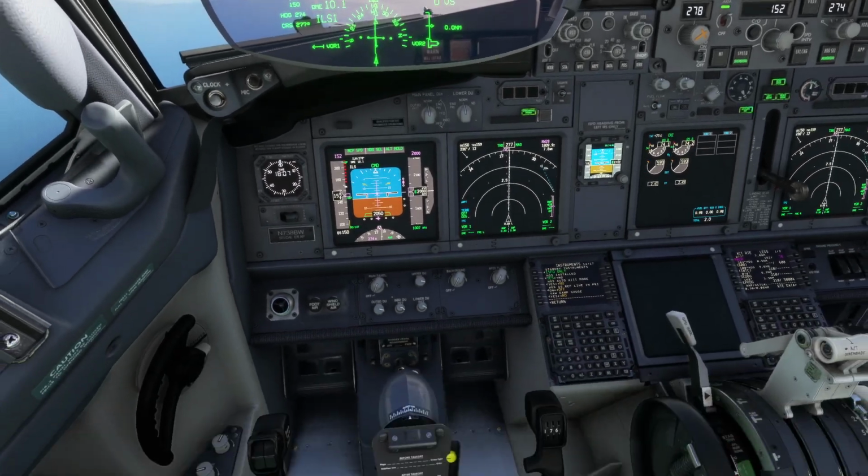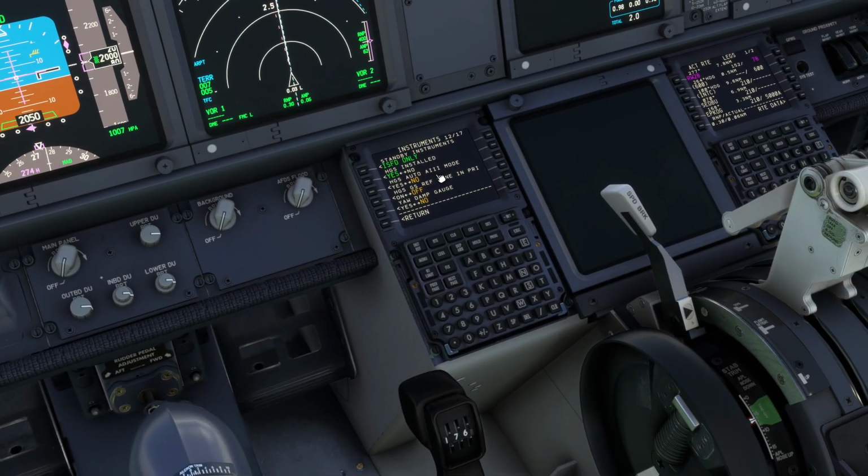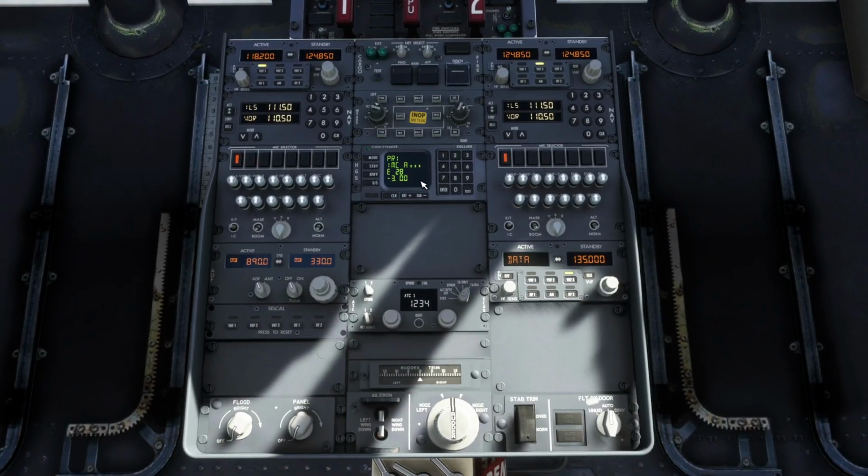The second option is related to the alpha 3 mode that we have for approach. You are not activating or disabling the alpha 3 mode. The only thing that you are doing is to select if the alpha 3 mode will pop up automatically during your approach. So if you say no, as it's written here, you have to come to your system and select the alpha 3 mode and then change it to the primary one, which is going to be the alpha 3 mode on the top.